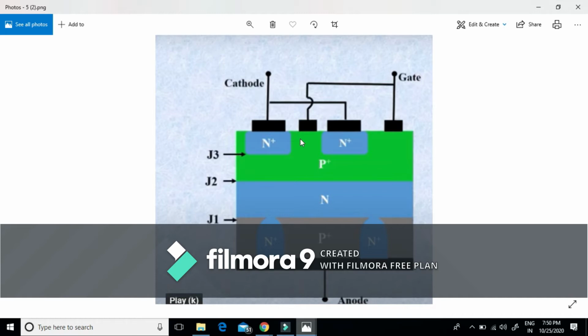Here, the highly doped gate region is used to obtain good turn-off properties, whereas the highly doped P+ anode region is required to obtain a higher efficiency anode junction to obtain good turn-on properties. But this highly doped anode affects the turn-off capabilities of GTO.